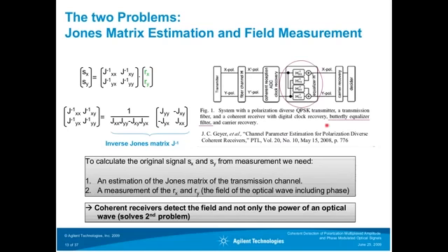But again, from this publication, what we are looking at: we have a transmitter, we have the fiber channel, the transmission channel, we have an A to D conversion, and then we have, in this case, a butterfly equalization filter. And we are looking at the simplest form of this equalization filter, which has only one filter tap, and that's the inverse of the channel matrix. That's exactly this expression. And then, of course, in case of a coherent receiver, you have to do carrier recovery and decoding of the signals, so you finally get your digital information back.